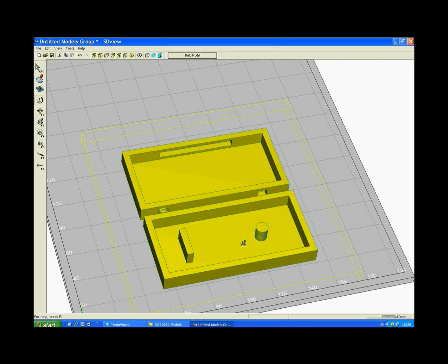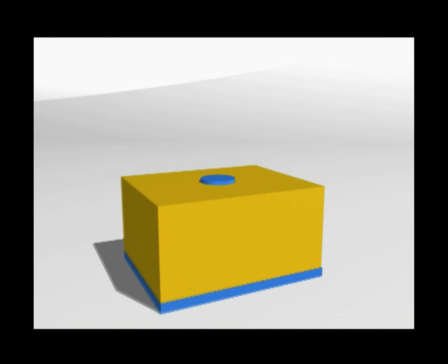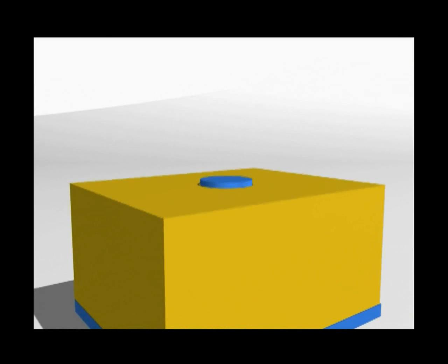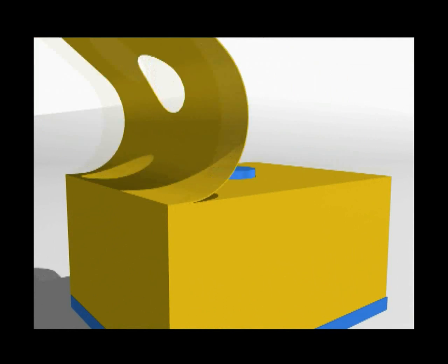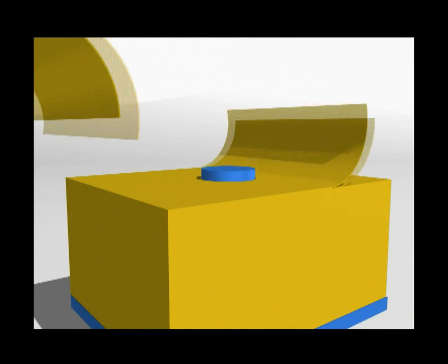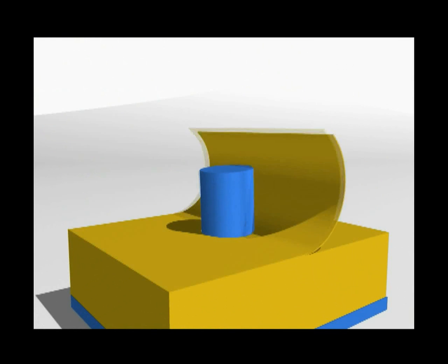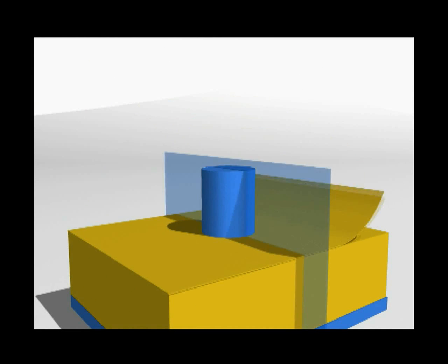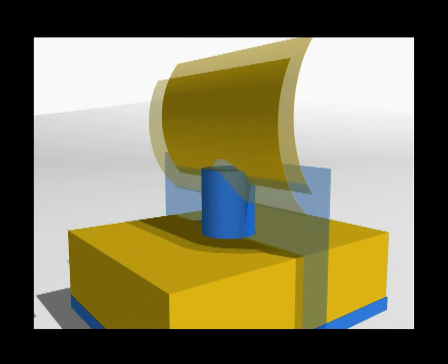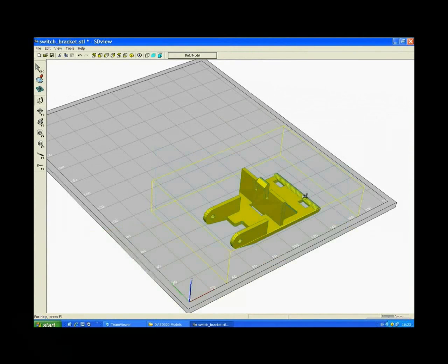When viewing the first model geometry, we see an open box with a wall inside and a post. If we attempt to peel and empty the support material without placing peeling cuts, we will run over both the post and the wall and may damage them. Peeling cuts can divide the wall and the post into areas that will be very easy to peel. We will now proceed to see another example.